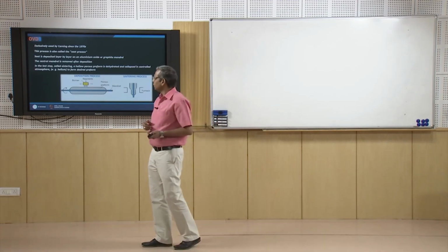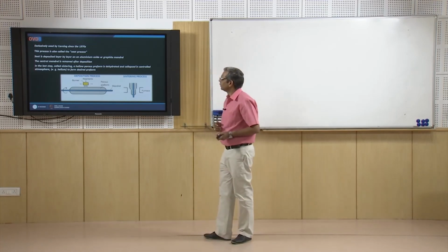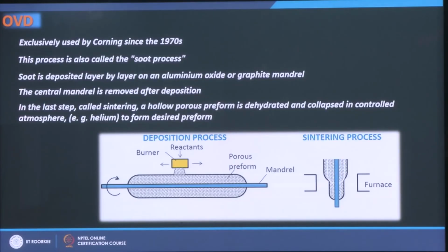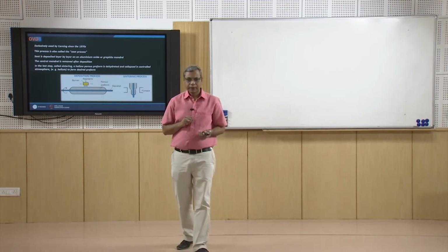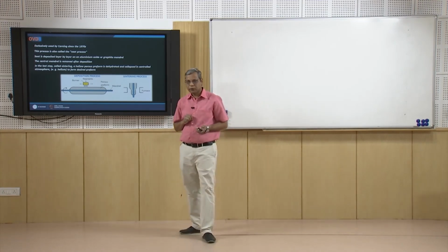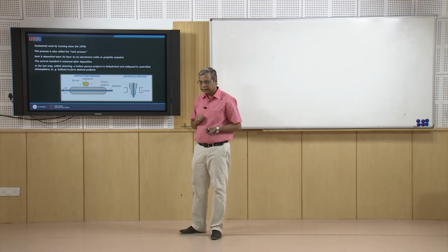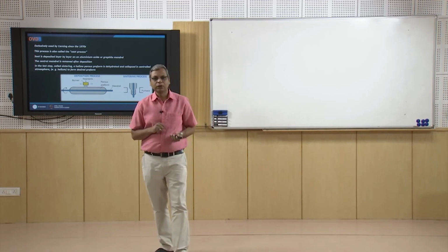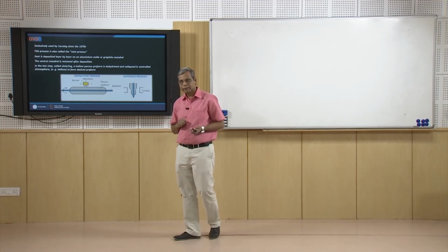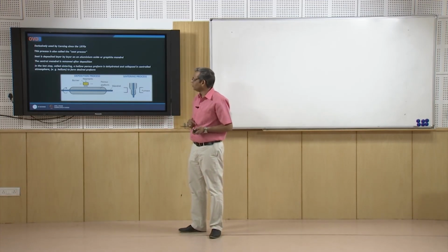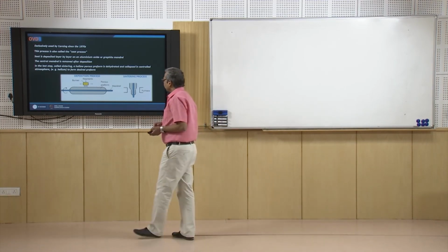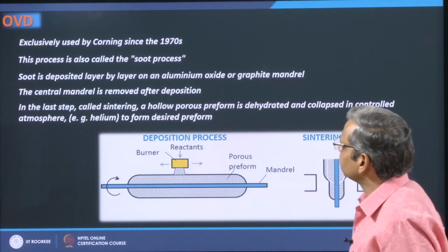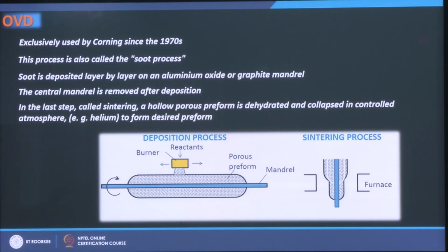and you will see initially this gob of glass is formed, and this is the fiber coming out. And then it goes through various stages. So, this is the fiber coming out, this is the diameter monitor. This is again, you can see the fiber coming down, and this is the take up drum.